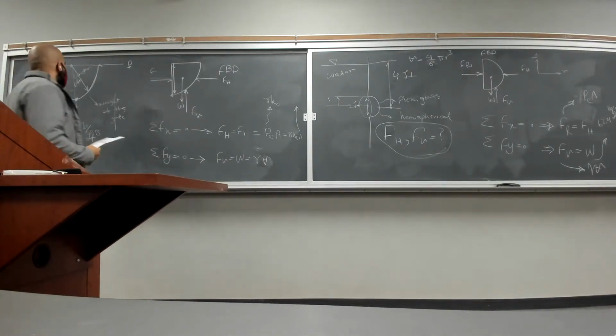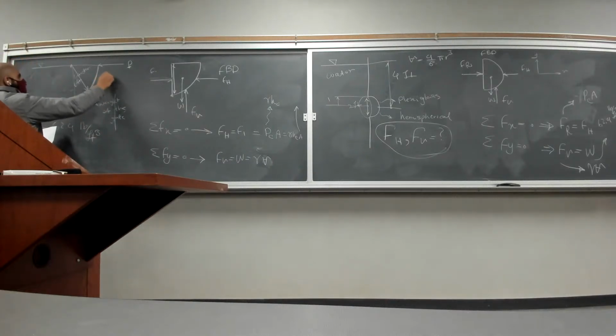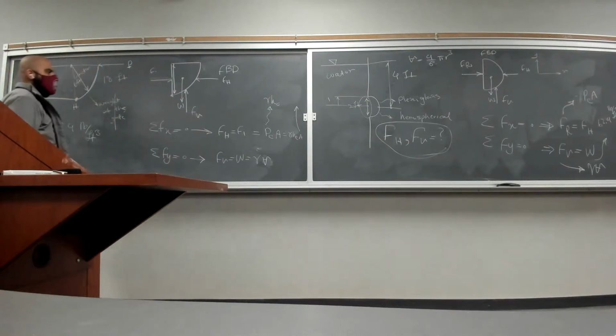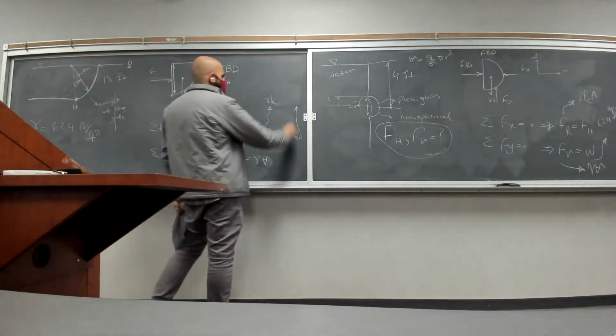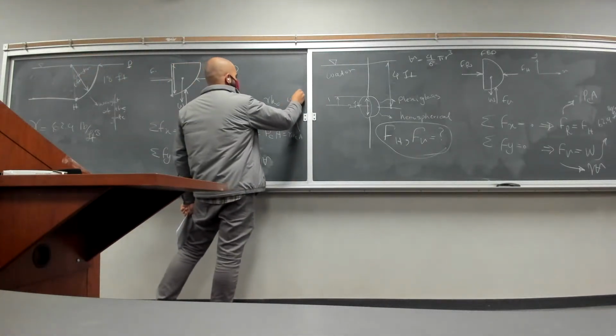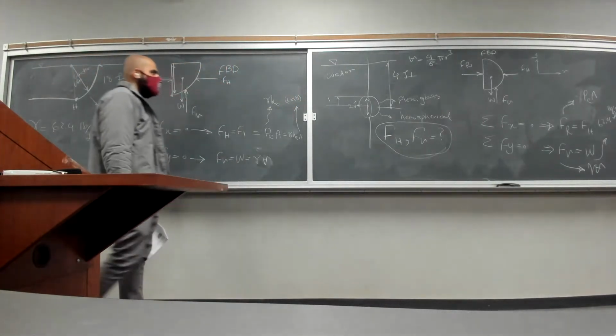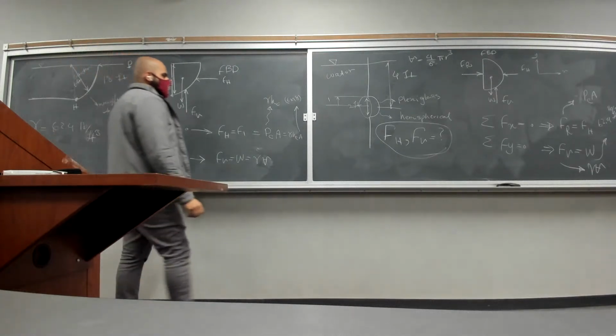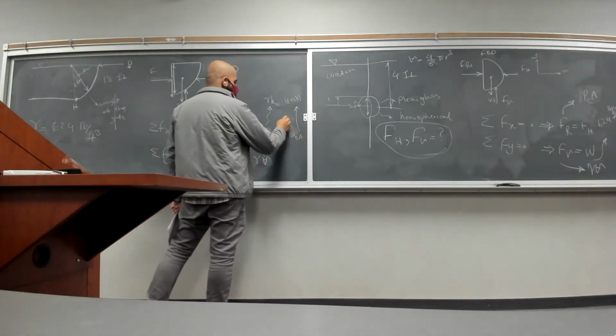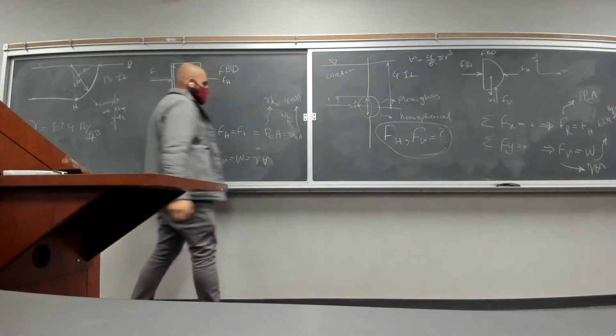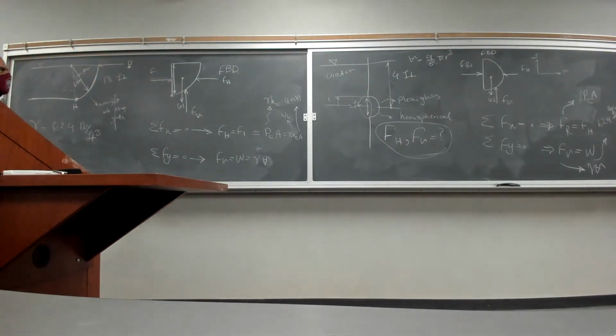It is perpendicular to the board. It is 18 feet. Right? It was given to us. It is 18 feet in this direction, right? So your A is going to be 6 multiplied by 18. H of C is going to be the centroid of this, which is 6 divided by 2. And gamma is 62.4.